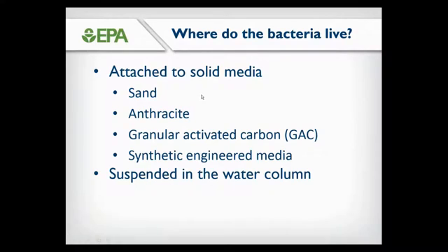So in a biological contactor, where does the bacteria live? They will attach to any solid surface, and these include solid surfaces of media that are typically used in drinking water treatment. So for example, filter sand, anthracite, granular activated carbon, and synthetic engineered media, which include things like pall rings, berl saddles, and raschig rings. Bacteria can also be suspended in the water column in a suspended growth